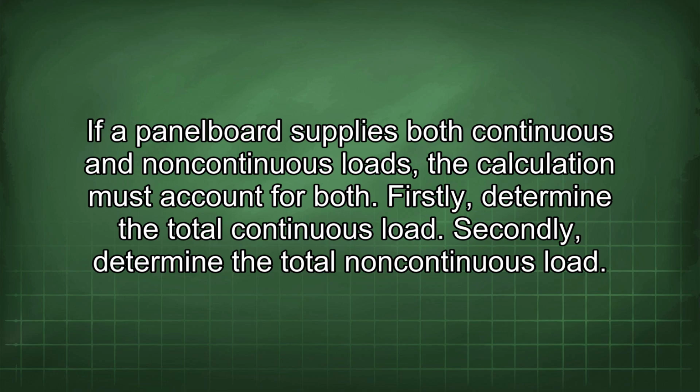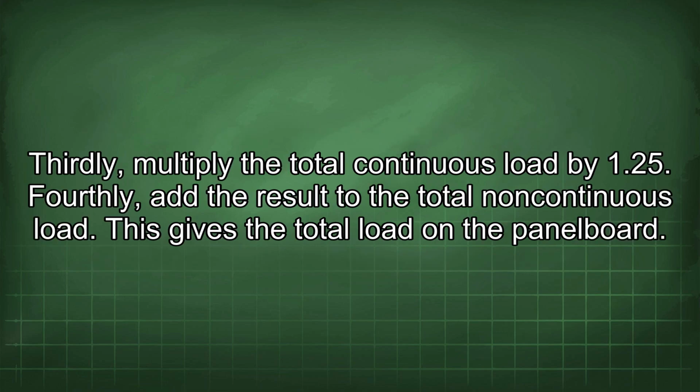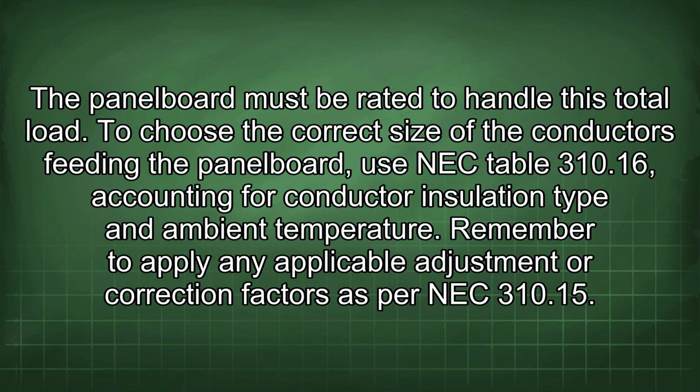Firstly, determine the total continuous load. Secondly, determine the total non-continuous load. Thirdly, multiply the total continuous load by 1.25. Fourthly, add the result to the total non-continuous load. This gives the total load in the panel board. The panel board must be rated to handle this total load.